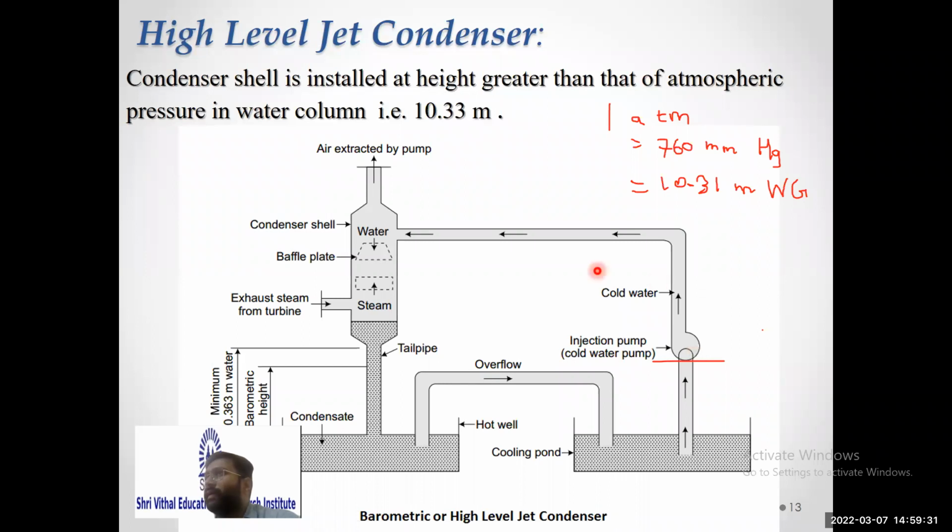Another detail in this case is that a baffle plate is provided. When the water falls on the baffle plate, it creates a sprinkle, like water falls in small droplets through this baffle plate, and then the heat exchange will be more.